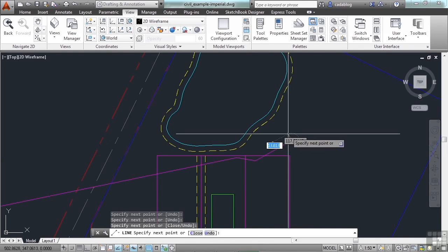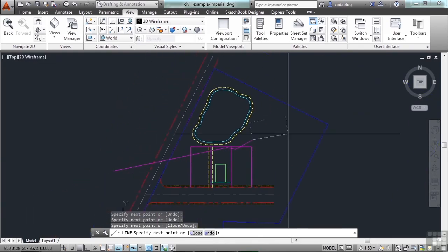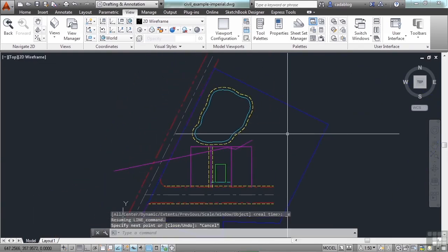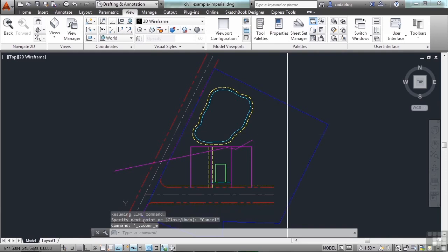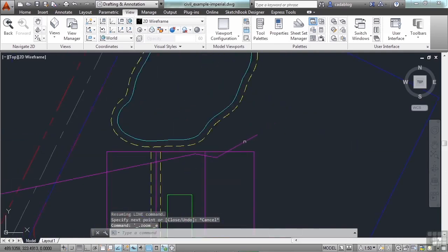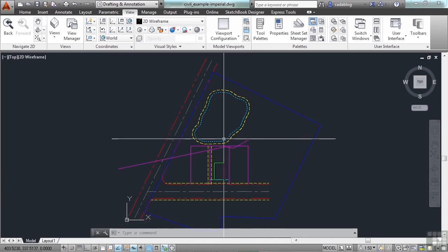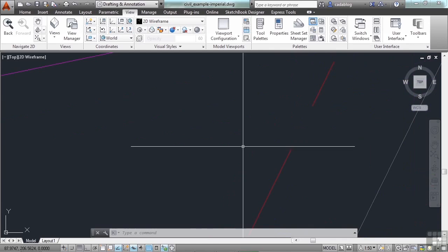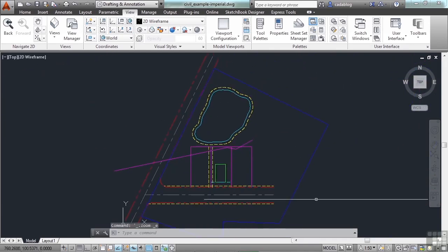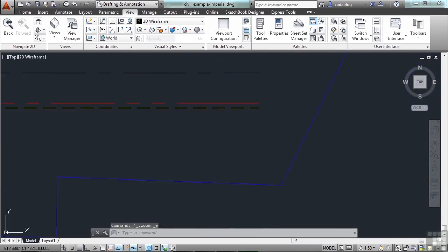And if you double click your scroll wheel, that's a zoom extents. So between the zoom extents and the zoom in and out, the majority of your zooming needs are done with your scroll wheel. Throw in the pan command, and I can navigate to anywhere very quickly.